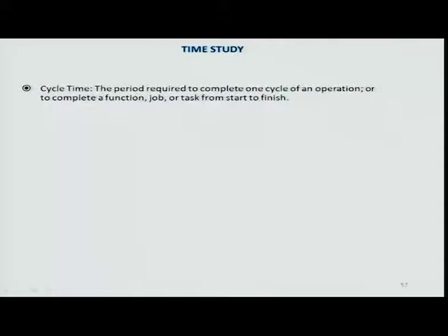Okay, so we will now start again detailing some of the time studies. I think I had mentioned about time studies that whenever such works and tasks are identified and a process sequence is being developed, you associate some time scales with respect to the independent work and independent tasks which are there in such work systems, and then the time scales can add up together to complete the whole operation, and we can call this addition of such time scales of the whole operation one cycle time.